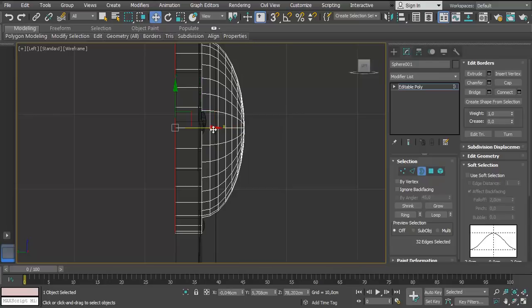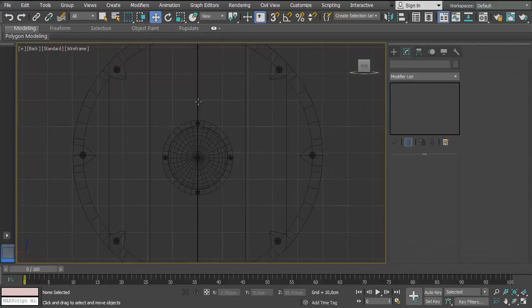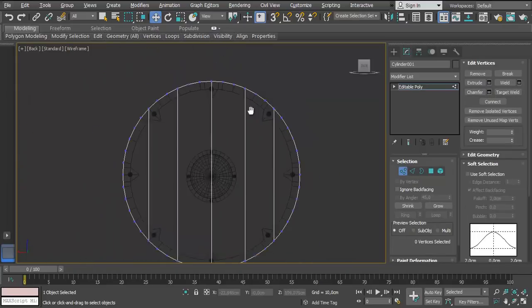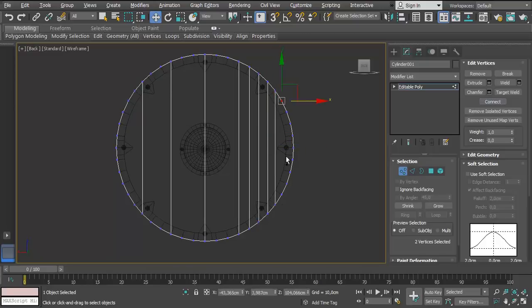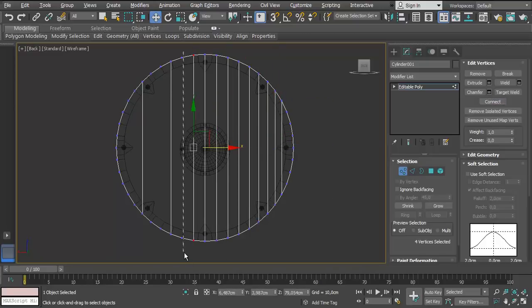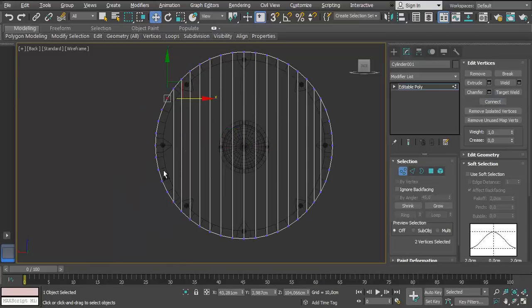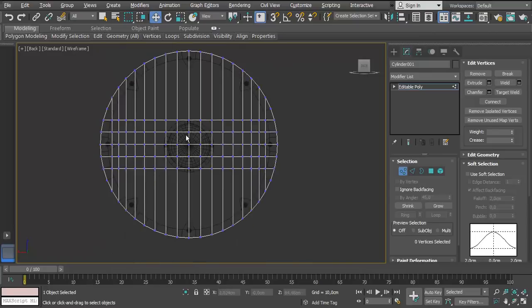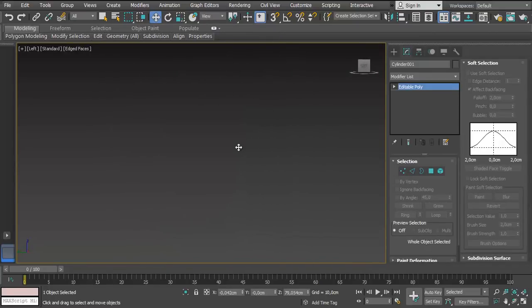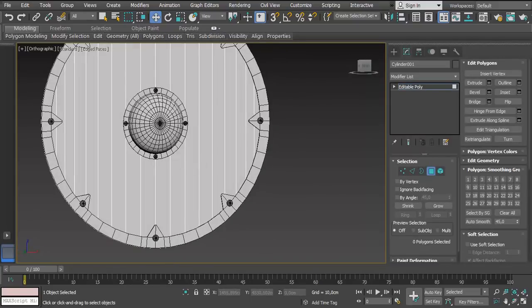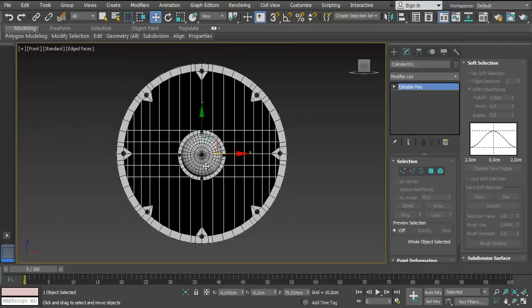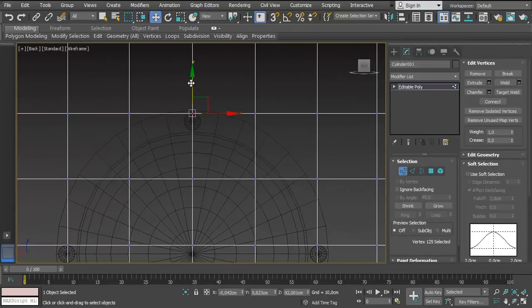Okay, now what we are going to do is create the other side of this hemisphere in the center of the shield. And as I explained before, we are going to create a handle from the other side. So yeah, it's going to be simple. But before we do this, you can see right now that I'm connecting all the vertices together, and this is going to be very important because we cannot leave vertices hanging right there without any kind of support and without any kind of connection between them. And we don't have to connect everything, because if we have quads, 4 sides on each polygon, it's going to be enough, especially if the supporting edges, which is the process we're going to work on later, do their job properly.